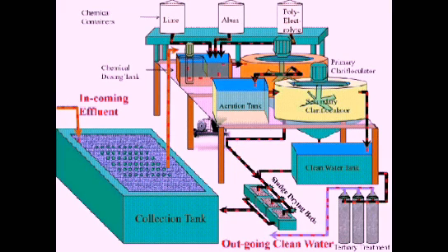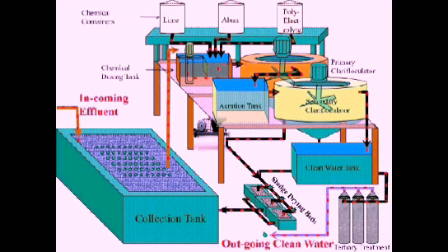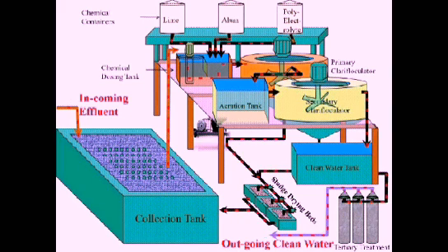And as a first operation, we stir the collected water in this tank either with the help of bubbles created by compressed air in case of a big collection tank, or with a stirrer in case of a small, maybe up to 50 kL collection tank. The idea is to have a homogeneous solution before we start any treatment.